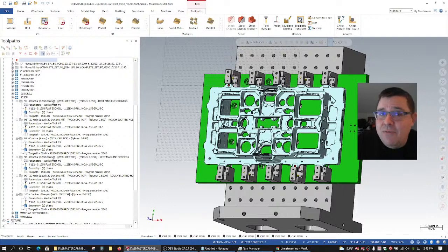So don't be fooled by the chips that are being sold for multi-core processing, because you can get an 8 or 16 or 32 core processor that works great if you're doing rendering. It works great if your software is built to take advantage of a true multi-core processing model. But for Mastercam, what you really want is a fast clock speed.